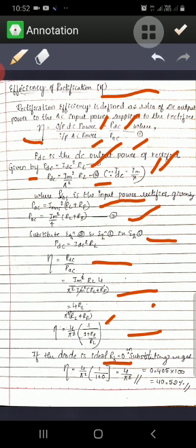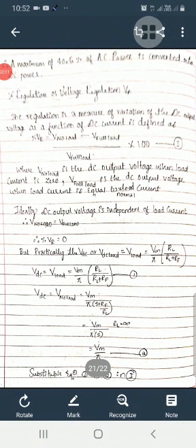0.405, which in terms of percentage is 40.52%. That is nothing but, for a half-wave rectifier, out of 100 units given, only about 40 are converted into the output, which is nothing but the efficiency of 40.52%. Therefore, a maximum of 40.6% of AC power is converted into DC power. So if you are giving 100 units of power as input, only about 40 are converted into DC output, and approximately 60% gets wasted.